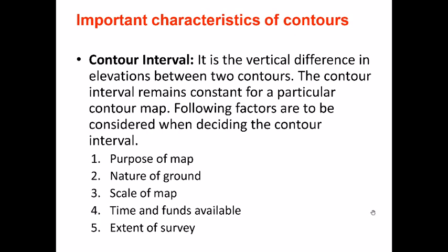So the contour interval remains constant for a particular contour map. So once you've chosen that, you cannot change it for different parts of the land. And the following factors are to be considered when deciding the contour interval, because this is the most important factor that you have to decide, because it really increases or reduces the amount of work that you have to do.